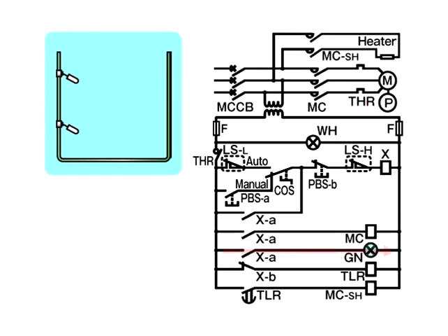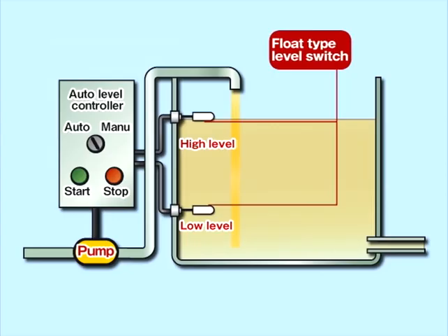As XA is turned on, the green operation lamp illuminates. As XB is turned off, the timer's coil is demagnetized. As the fuel oil transfer pump usually operates in auto-control operation mode, the changeover switch is usually switched over to auto mode after confirming that pump operation has been initiated. Pump operation continues because X remains in self-holding state after switchover.